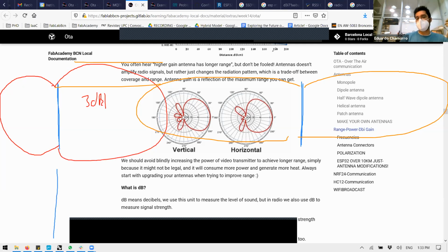Something that is really easy to change, for example in Wi-Fi routers for house applications, is you can have a 1 dBi antenna, shorter range but really omnidirectional, or a higher gain antenna. For example, a 10 dBi antenna is usually slightly bigger. That will be really flat. If you aim the antenna correctly, it gives you more coverage, and you don't waste network on the top and bottom neighborhood.